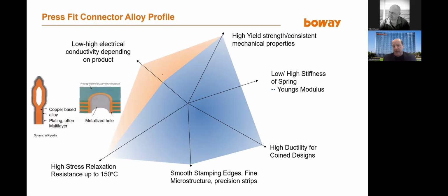If we go to press fit applications, as well, something we see revolutionary in the automotive industry, where actually a pin, it could be just a normal pin, or it could be something with a spring, an eye of the needle, or even with something coining, is connecting directly into a metallized hole and with very high spring forces. And here again, the key points are relaxation, the mechanical strength you have, how stiff you can make the spring, or how soft you want it in order to have the right insertion and withdrawal forces.